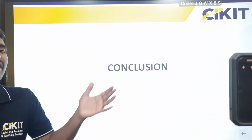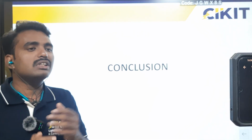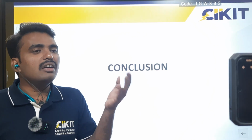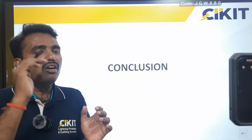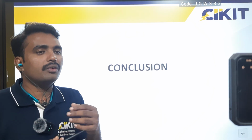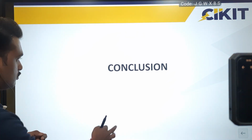The third point: if the same building is located in different areas, is the same level applicable? It is not applicable, because environmental parameters and the number of lightning strikes come into the picture. We cannot directly say that the lightning protection will be the same for buildings in different locations. We have to perform the risk assessment separately for separate structures.